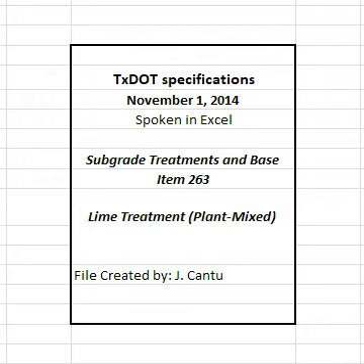Notify the engineer of proposed sources of materials and of changes to material sources. The engineer will verify that the requirements of this item are met before the sources can be used. The engineer may sample and test project materials at any time before compaction. Use TEX 100E for material definitions.